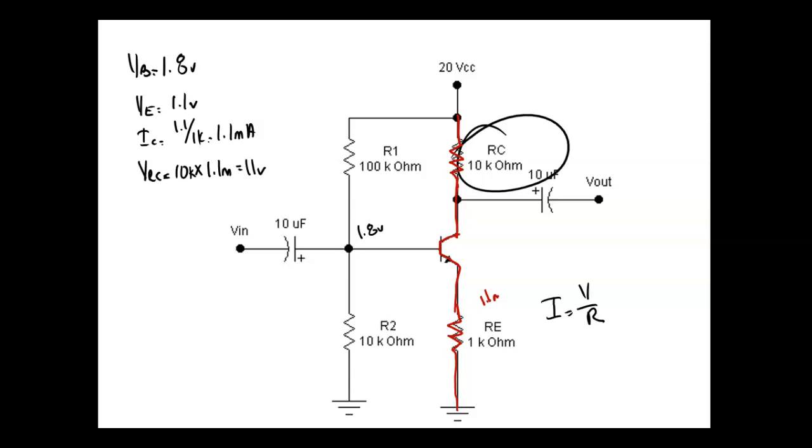So now these resistors have a function in life besides doing what? Creating heat. We use these resistors to set the bias. So we use series resistors on Zeners to keep them from burning up, to drop the difference between the unregulated voltage and the regulated voltage. We use resistors on LEDs so we can put 5 volts across them even though they drop 2 volts, right? You understand? So now you have a function of why we want to use these resistors.